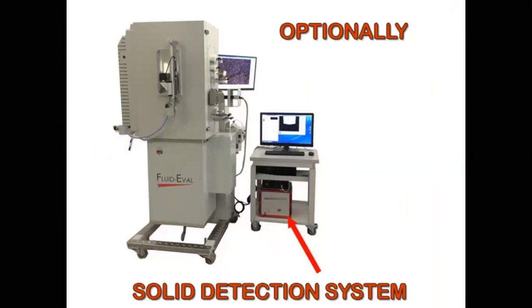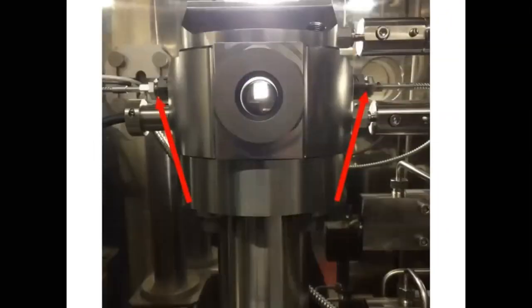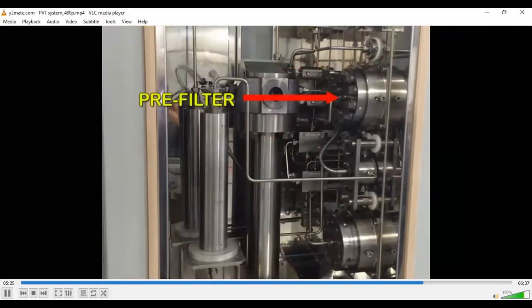Optionally, a solid detection system can be added to the assembly, permitting the determination of asphaltene onset pressure and wax appearance temperature. An optical fiber generates near-infrared light through the reservoir fluid, and the resulting transmitted light is utilized to deduce the presence of asphaltene fluid at each state of pressure and temperature. An organic solid filtration system is also available. It is based on two high-pressure, high-temperature filters. The first removes the inorganic particles contained in the oil sample during transfer from the sample cylinder to the PVT cell.